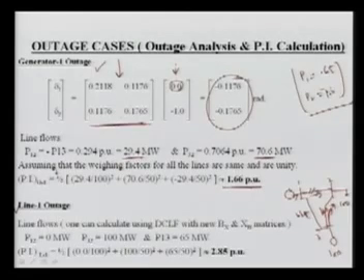Now this is going to change, so we can again form that B matrix, then we can go for the inversion, and then we'll find that we are getting this power, and then you can form this PI value. You will get a similar value here, 0 upon 100 because of 0 power, and finally you are getting 2.85 per unit for this case of line 1 outage.